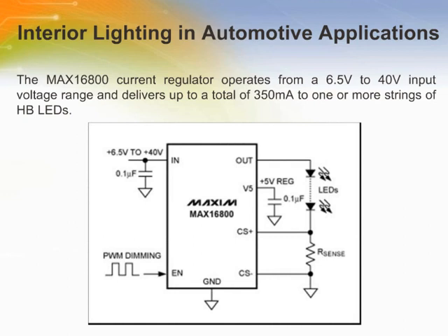The color of an LED varies with the current flowing through it. Dimming LED brightness is therefore better achieved by pulse width modulating, PWM, a constant current than by actually changing the current magnitude. The MAX16800 dims LED brightness by applying a PWM signal to the enable input. The current through the LEDs is turned on and off at the rate set by the PWM signal. In order to reduce the radiated EMI during PWM dimming, the MAX16800 uses wave shaping circuitry to smooth the switching edges.